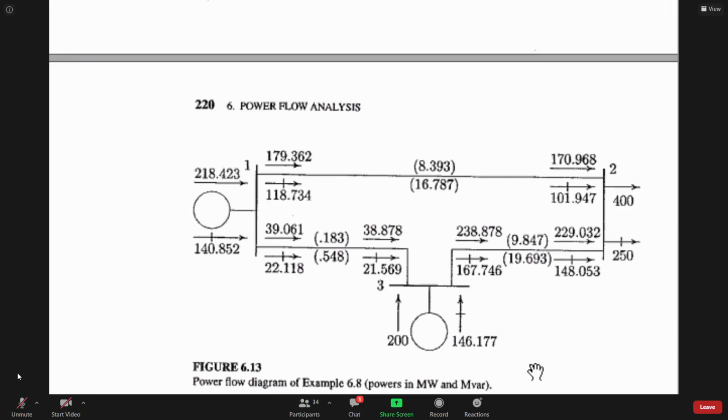So up to now, what we have discussed: you know how to generate, if a circuit is given in terms of impedance information, the equivalent admittance. Then you can draw the admittance diagram. From that admittance diagram, we can find the admittance bus, Y bus, right?